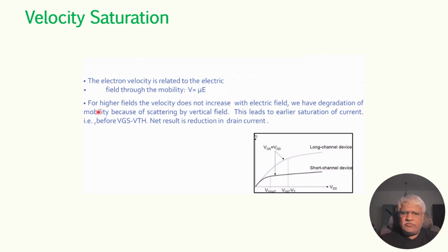Here, if you observe, when the voltages are increased, that means higher electric fields, based on the doping levels and all, a critical value will be reached, especially in short channel devices, after which the drain current plateaus. It doesn't increase, it saturates, I mean. So this is due to scattering phenomena again. This is the effect of the scattering phenomenon.